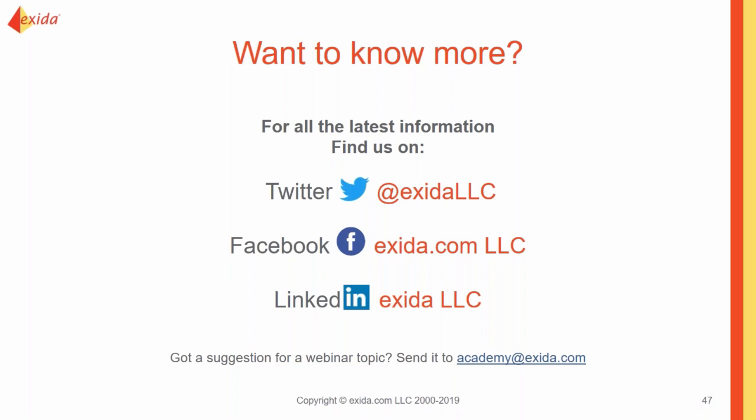So this goes back to your risk reduction calculations. You're going to need to know that limiting factor. If we're only talking about systematic capability, you can use whatever the highest systematic capability you need is. So for example, you only need a few SIL 2 CIFs. Everything can be a SIL 2, and you can just know that you're fine. However, you don't need to have SIL 2 equipment in a SIL 1 CIF. You can have specific equipment for your SIL 2 CIF, specific equipment for your SIL 1 CIF.